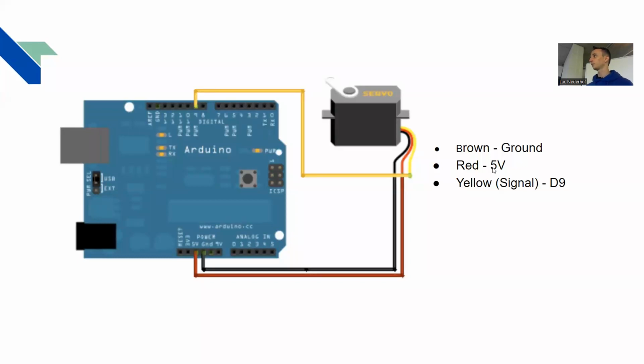They will not run at 9 volts straight from the battery. It's not only that you will probably damage the motor, it's that it will straight up not work at all, because it is expecting that 5 volts, and it's expecting the PWM signal to match that 5 volt expectation.